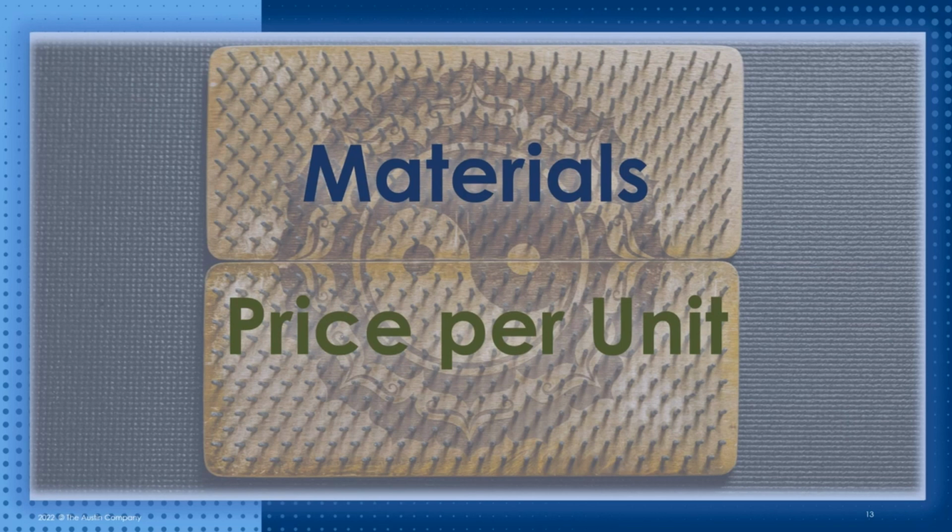Now, it's important to note that unlike the static nature of the materials data which we have harvested, the price assumptions which we assume are dynamic and changing. Factors such as geographical region, economic climate, and material worth will all dictate which batch of price assumptions are right for a particular project. The team should leverage experienced estimators, price databases such as RS Means, and subcontractor contacts to obtain reliable price assumptions.